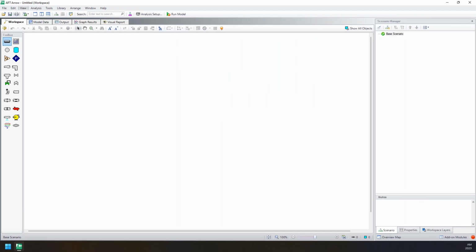So here back in the software on the left of the workspace, we have our toolbox where we have different junctions that we can use for our model. In our case, we're going to drag a tank onto the workspace. We'll drag our control valve, which we're going to be using to size our orifice, and then we can drag another tank onto the workspace. The junctions can obviously be much more complex. You can capture heat exchangers, for example, and all of the different heat rates and models of a heat exchanger to consider. We'll touch on that a little later.